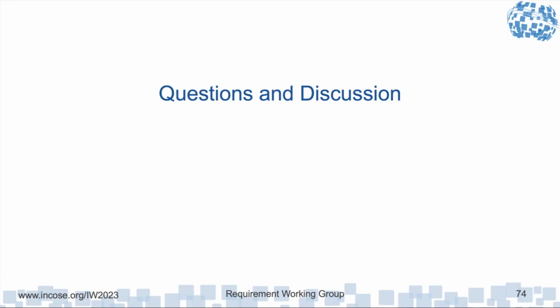One of the things is this filtering process. Even though you have all those standards, make sure which ones apply to the processes, which ones apply to the product component itself from a design technical standpoint, and which ones apply to how you're going to attain a certification or qualification of each of those components. That filtering process will put everything in its place. A lot of times I see a lot of standards being called out, but they have these different types and people really haven't said anything about this.